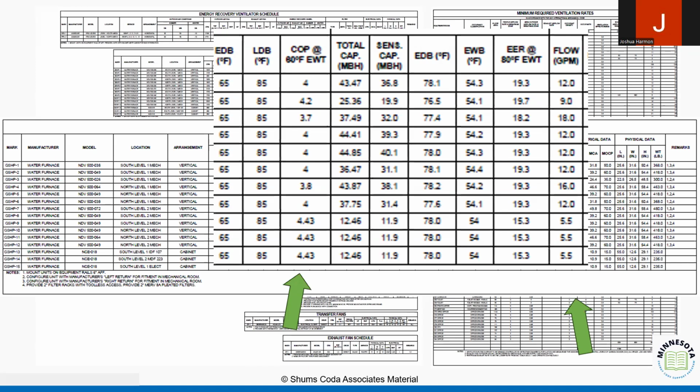COMCheck is one method of demonstrating the trade-off for section 5.6. It's not the only method. We can do other methods, there are other systems. This one is just free, which is why most people use it. Then it asks about the energy cost budget and the performance measures. Those use different software for simulating that energy calculation and documentation, but they can use COMCheck for documentation as well.